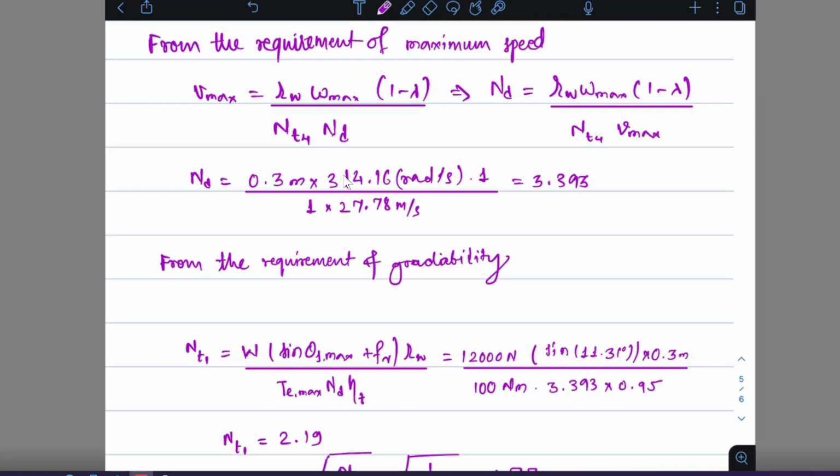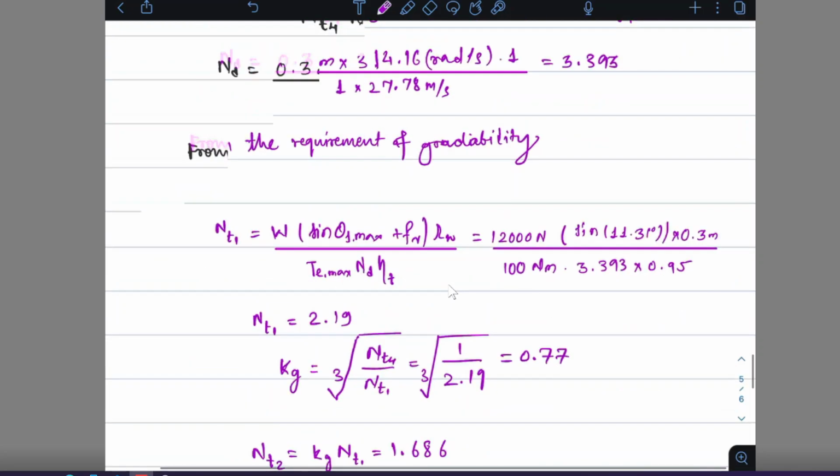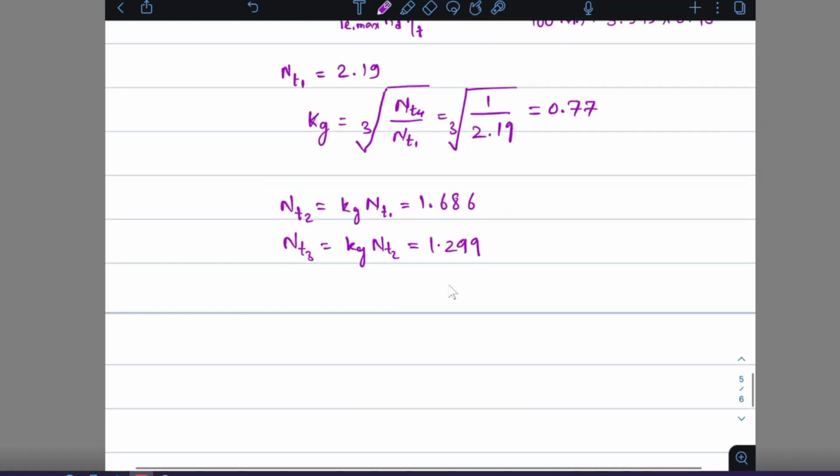Generally, this course is taken by our fifth semester undergraduates, followed by vehicle dynamics in their sixth semester. So it's kind of a continuation. We are neglecting lambda here because we do not want to go into a discussion of how the wheel slip ratio works and how to calculate it. It's more of a dynamic quantity, whereas the relations we are working with here are algebraic relations. So that is the intention why we are neglecting lambda. I hope that answers the question.